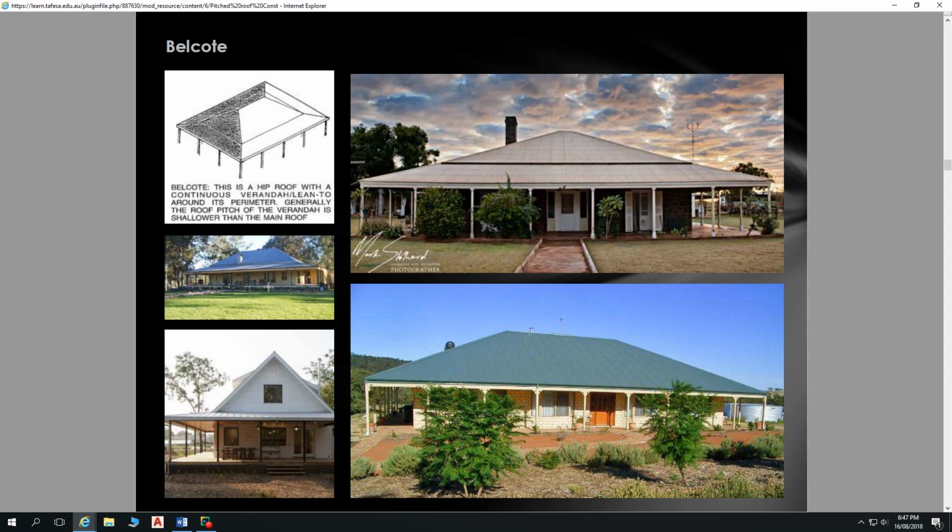Waterproof membranes can be problematic, I'll give you that, and I don't know enough about them to say how they should be used. But certainly it allows, once again, a great deal of design flexibility, because a waterproof membrane enables you to have cast on site concrete roofs, or even green roofs, where you have a roof covered by vegetation of sorts and you need a waterproof membrane under that.